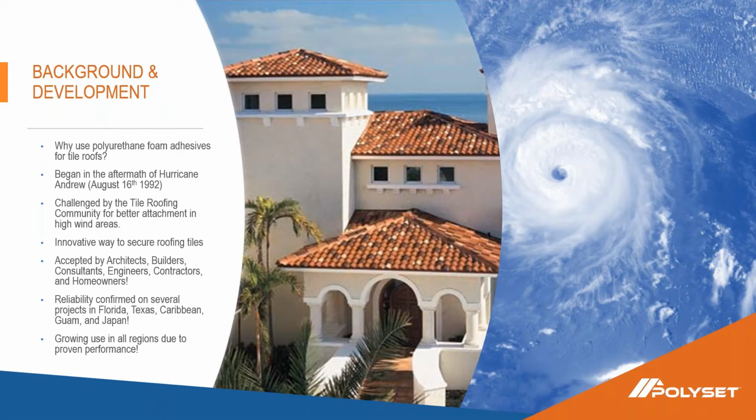After Andrew, a lot of those systems back in the day were installed with what the industry refers to as a mud set system, which is a mortar cement-based patty underneath the tiles. The industry saw the destruction, and they were looking for a better way to attach these concrete and clay roof tiles. So that's how the product emerged.